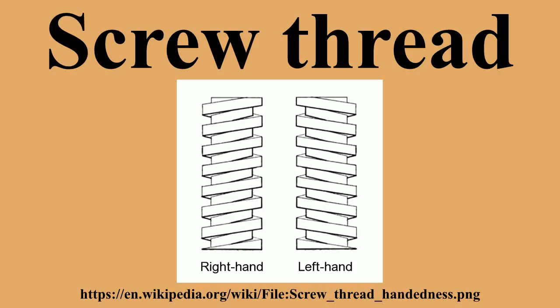However, UTS and ISO threads are not sharp threads. The major and minor diameters delimit truncations on either side of the sharp V, typically about 1/8 of the pitch, although the actual geometry definition has more variables than that. This means that a full UTS or ISO thread has a height of around .65p.